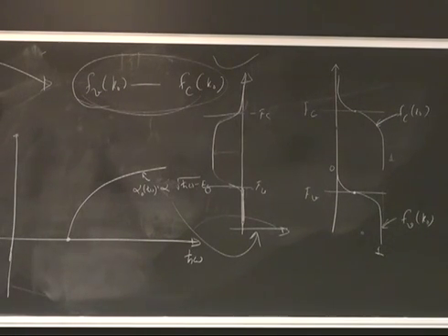What are you controlling? You are controlling, by electrical injection, two quantities. One is Fc, the quasi-Fermi level of electrons, and Fv, the quasi-Fermi level of holes. Those two things you are controlling. How are you controlling them? By the voltage you apply. So remember, you are in a p-n junction, and this is the active region of a p-n junction. If the voltage applied is 0, your Fc and Fv are equal. There are not two Fermi levels. There's only one. This is equilibrium, right?